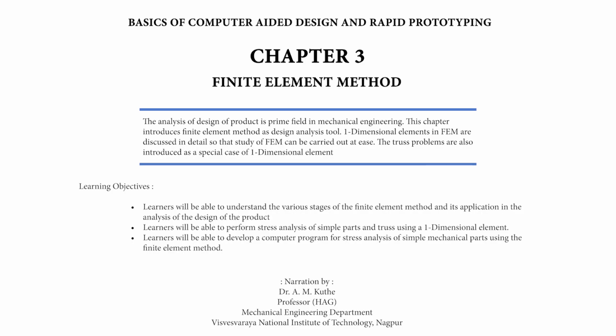Refer figure 3.6. The triangular element is the basic element because the quadrilateral element can be considered as the combination of two triangular elements. The displacement of nodes of the two-dimensional element is expressed in two mutually perpendicular directions. The quadrilateral has simple geometry, hence it is preferred over the triangular element. The two-dimensional element is used in the problems of the plane stress and plane strain.